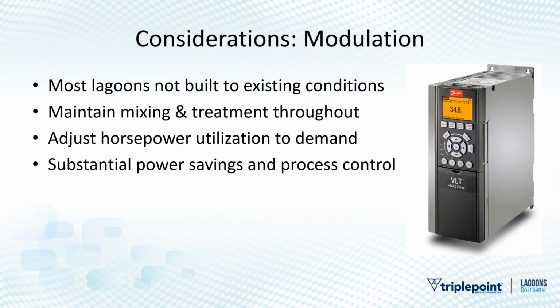So if you have an ability to turn the aeration down in an effective way, you can save power so you don't over aerate. If you have a surface aeration system, you can turn off individual aerators, which will definitely reduce maintenance because you're not utilizing equipment as much, and it will reduce power. It does tend to lose mixing in whatever area those were in. So there is a consequence to that if you're turning off surface aerators.